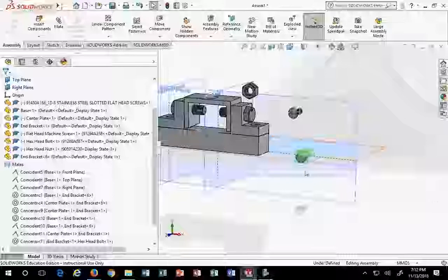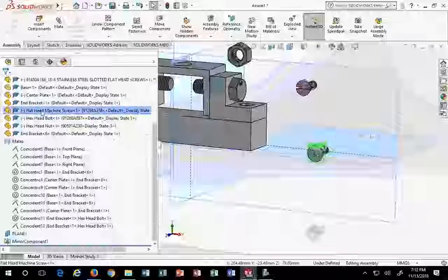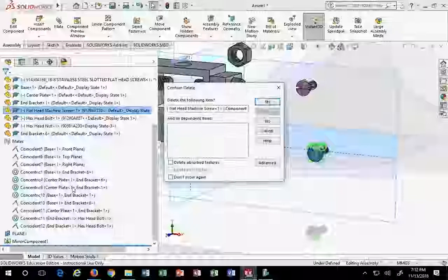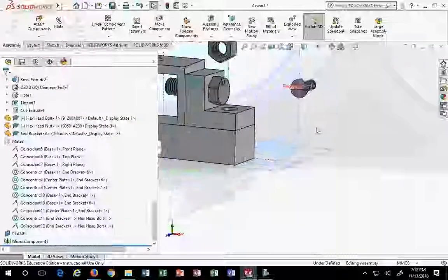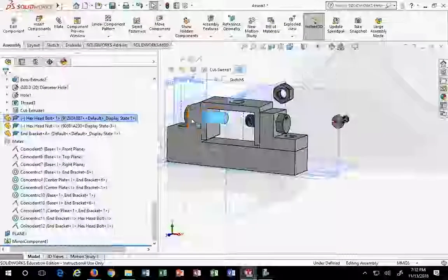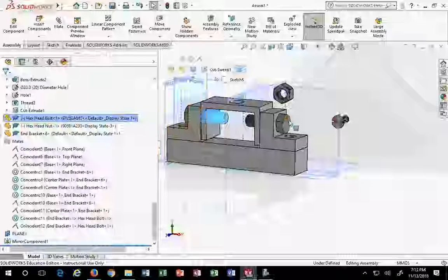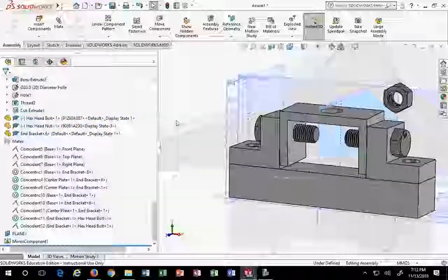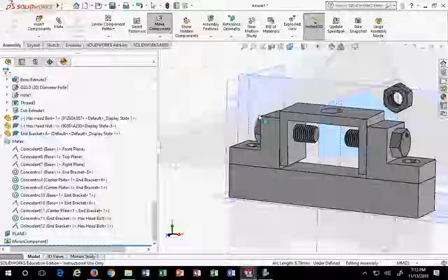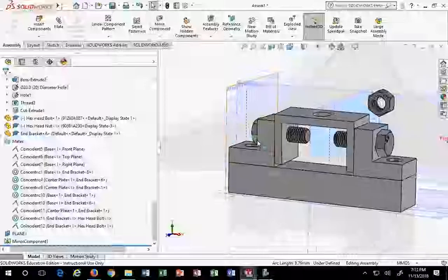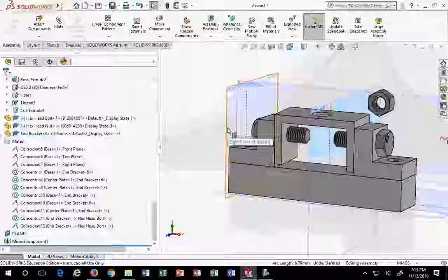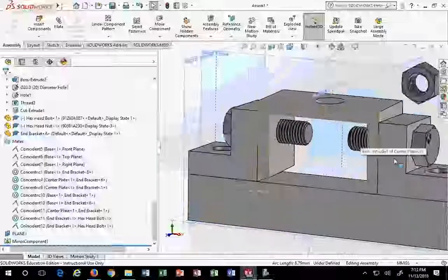This item right here. What is this one again? That's this one. Right mouse button and delete. All you do is get rid of that one. But you only see this listed once. Whenever you mirror, you only see the item once, and it is a complete partner to its original. See that? Whatever you do to the original happens to the mirror. It's like the right and left hand of it. Does that make sense? Just be aware of that.